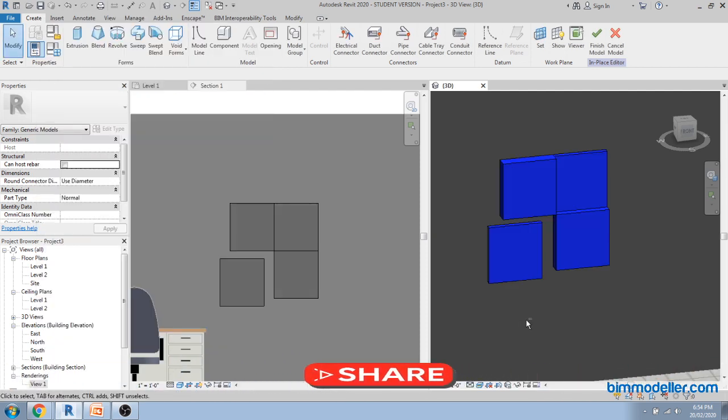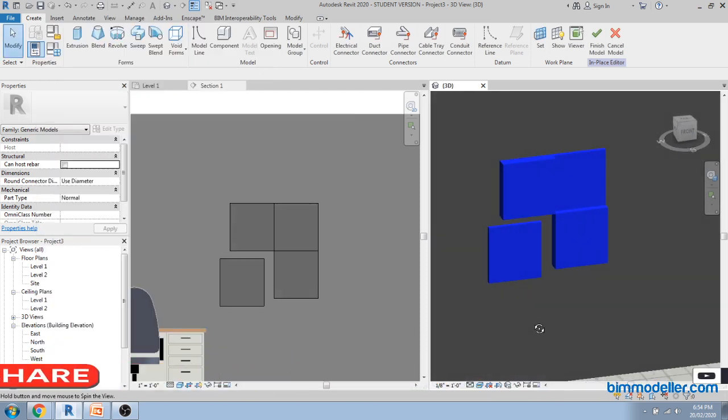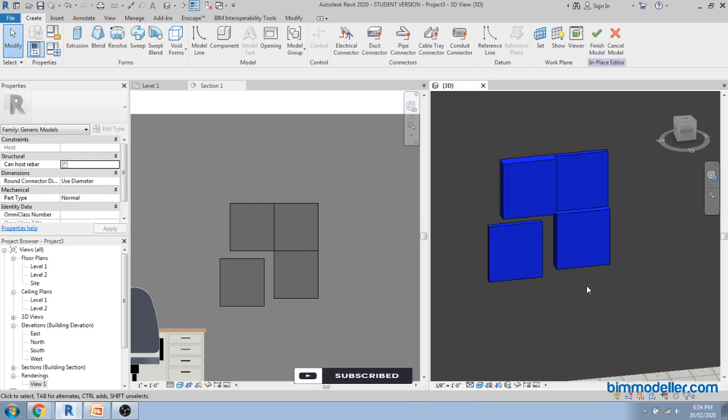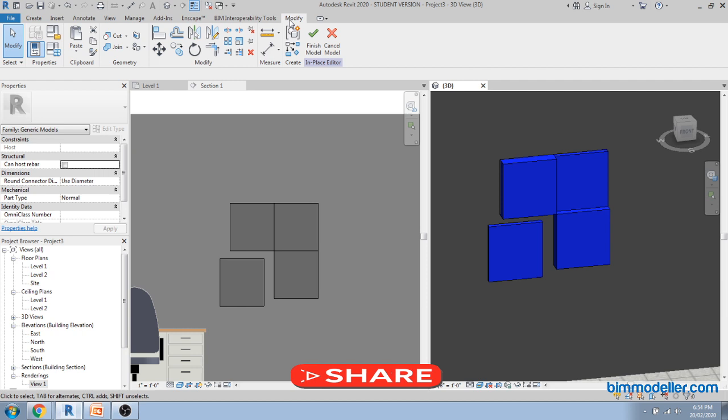Say okay. Now these elements have blue color, but we don't want the blue color on all the faces. I like to have different colors on the faces. So how do we assign the face material? Instead of assigning it to all the faces, all other sides will be blue and the front face will be in a different color. This is how the paint tool comes in handy.